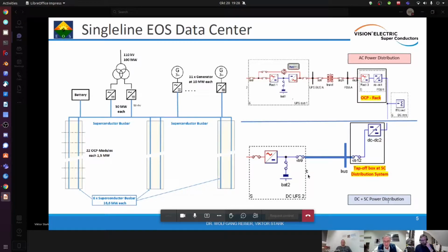So this does not give additional problems. And I've spoken to data centers where the operators are telling me that year by year they have a failure of power supplies in the racks, and they have to exchange between 5 and 10% of the power supplies simply because they are not working correctly because of unbalanced potentials between A and B power supplies. That is possible. Not in all data centers, but sometimes it's possible. Yeah, that is definitely an issue.